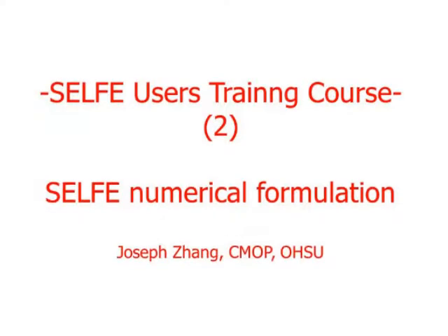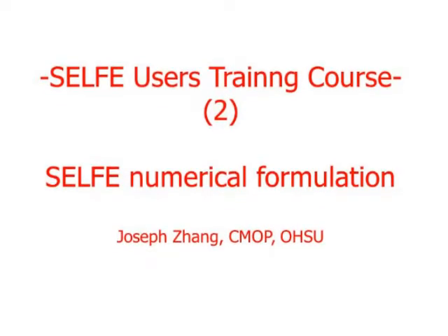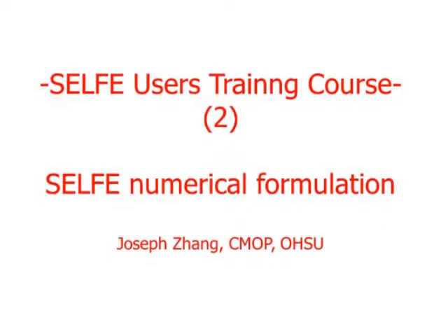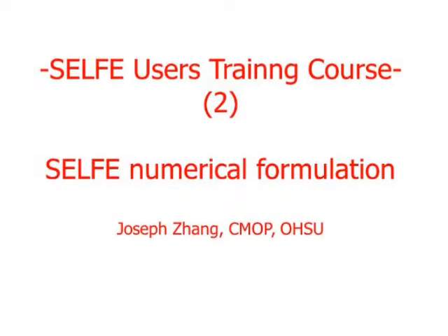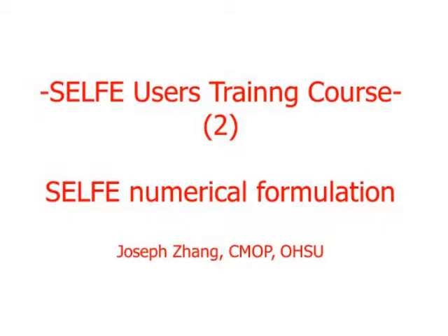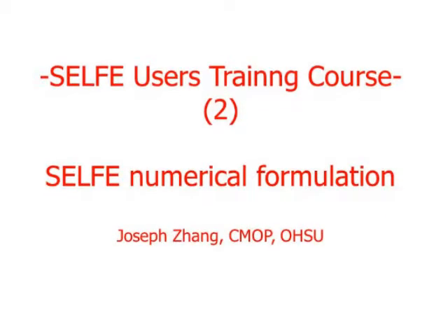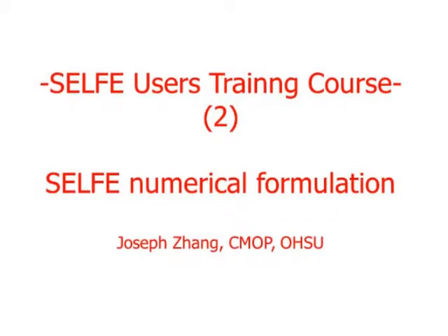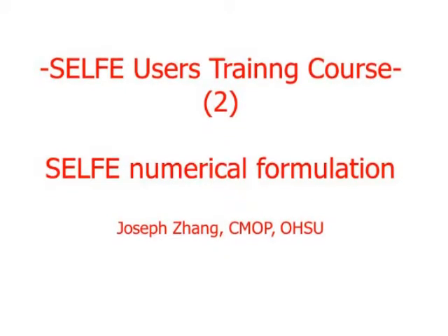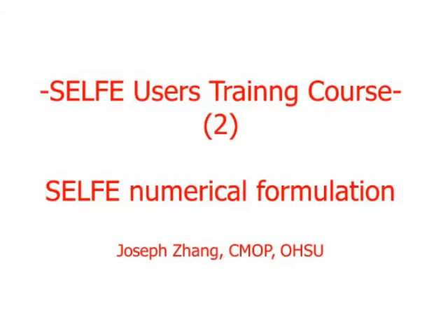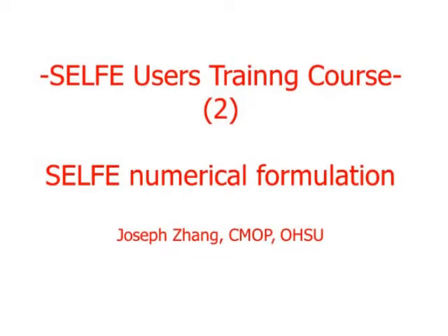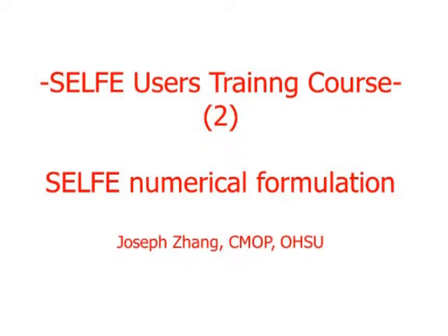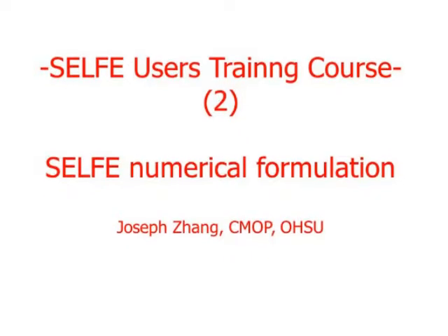So the shape function is a very important concept in finite element. Shape functions are primarily used to approximate the unknowns. So phi i are used to approximate the unknown u, where u_i is the functional value at each node. For an unstructured grid, nodes are defined as vertices of the polygons.